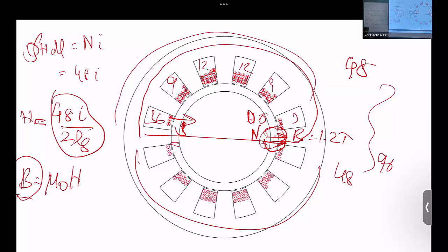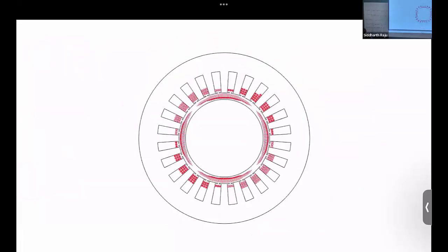All right, so you can do either thing. You can either double the number of conductors and increase your torque, or you can reduce the thickness of your yoke. Previously we would have had to have some large thickness in the yoke because all the flux lines pass through this, and flux divided by the area is going to be B. If the area is not large enough, your B field is going to be quite large, the motor will saturate, and the reluctance will be large. So your yoke thickness would have to be quite large.